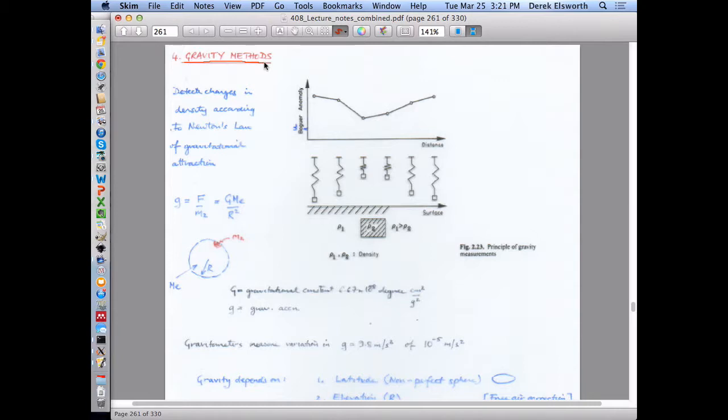And so you can use gravity methods to basically discriminate places where you have lower density materials. And so the ultimate lower density material might be a cave in karst, where you have air in the subsurface versus the material around it. And so the gravitational attraction on a weight in an instrument to a pocket of air versus to a pocket of rock is different. If you have something on a spring, it'll be more heavily pulled to something that's rock than to something that's air.